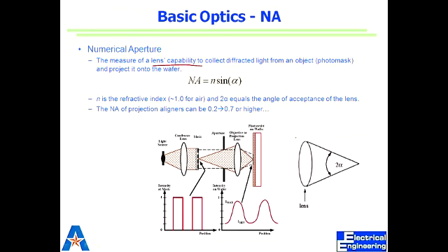So, does the concept of numerical aperture apply when we're doing contact printing? Like, does it degrade to infinity or 1 or something? Do you have a medium in between when you are doing contact with, I suppose, photoresist? You just transfer your energy right away, right there. I see. Contact printing. So you need a lens or a medium in between for it to even apply. What you see is what you get. There's no diffraction. It's right there. So probably the internal reflection of the resist might be more prominent.